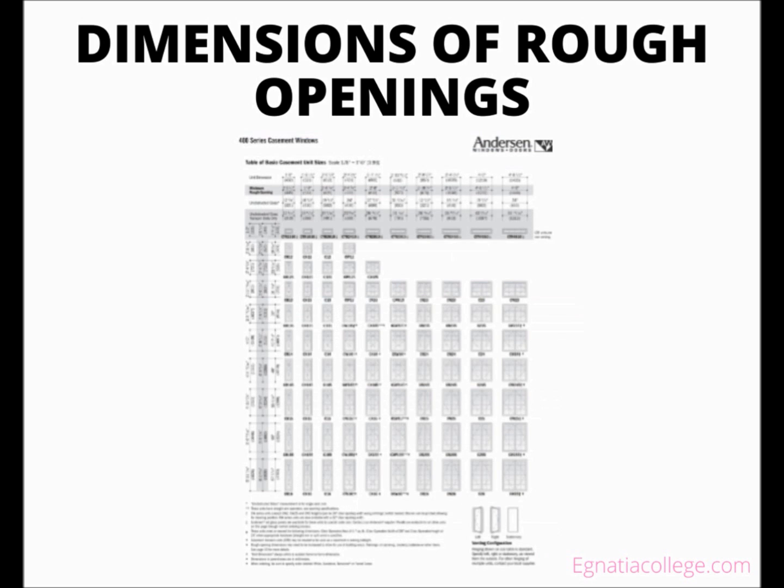The rough opening dimensions are not usually given on the drawings. They should be obtained from the manufacturer. Window manufacturers do not list the same size information in their literature, but they do list the rough opening size. Other sizes they sometimes list are nominal size or unit dimensions, approximate overall size of the window, and glass size, the size of the actual glass in the window.